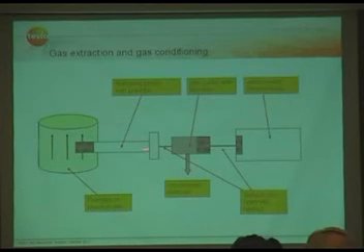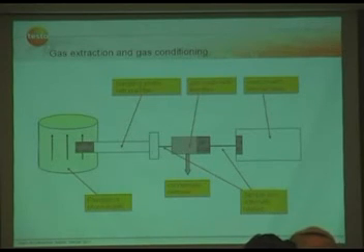Then we have the sample lines between the flue gas probe, the chiller and the analyzer. Those lines can be heated up if necessary, or they can just be a regular line or a Teflon line. And then we have the analyzer with internal filters just to protect the sensors, not to get any soot or particulate to the membrane to stop them working. This is basically how a system looks like.